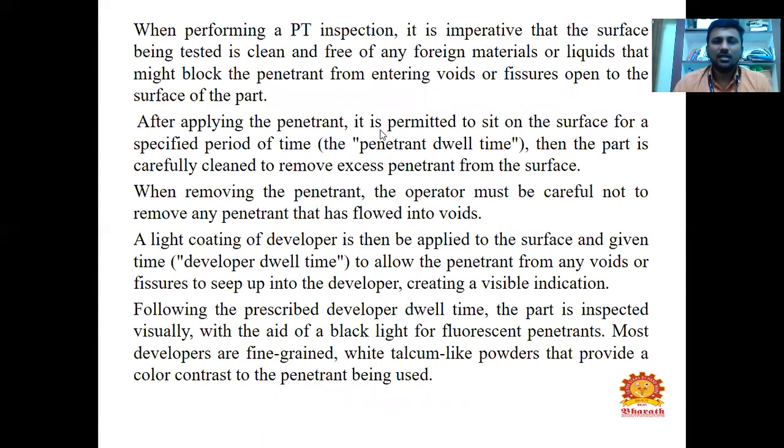When performing the penetrant testing inspection method, it is important that the surface being tested is clean and free of any foreign material or liquid that might block the penetrant from entering voids open to the surface of the part.